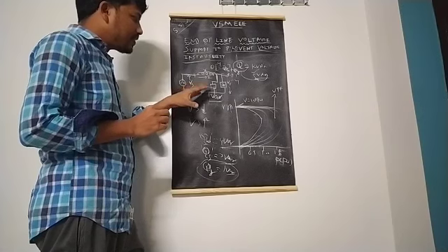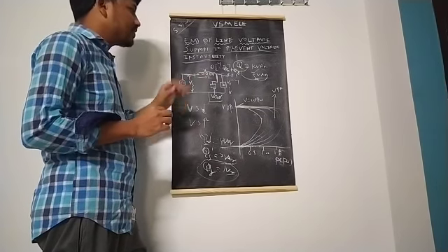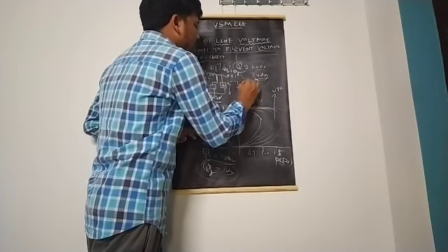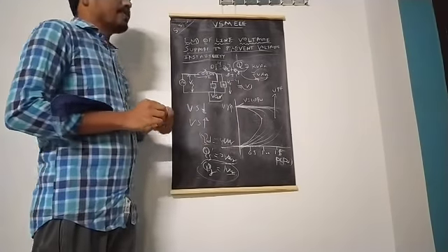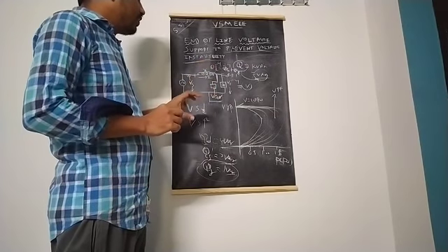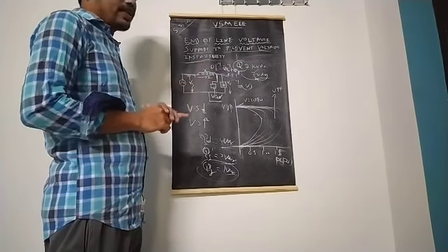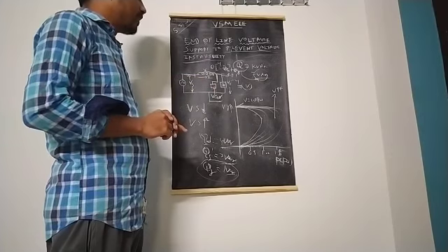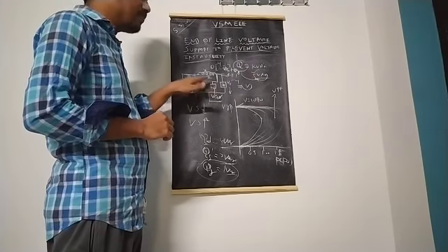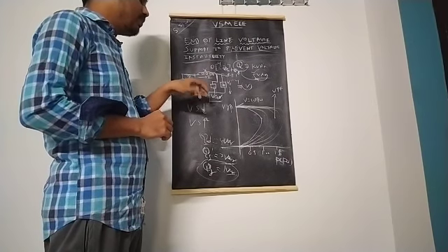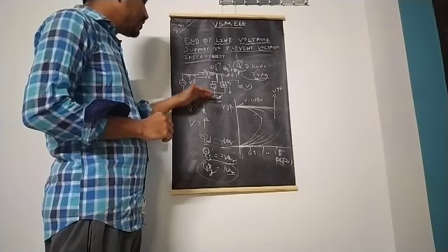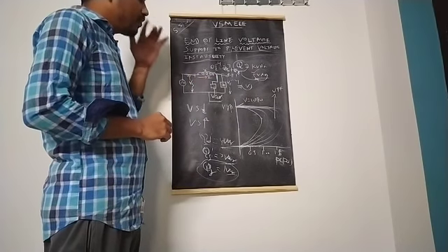While providing this reactive power, which indirectly supports the voltage, these shunt compensation devices support the voltage at the receiving end. This is the importance of these reactive power compensators. The reactive power compensation device may be variable impedance type, that is, it may be inductance type or it may be capacitance. With capacitance the stability increases, while with inductance the stability decreases.